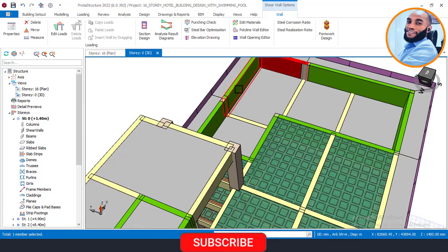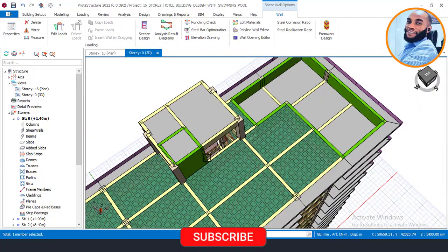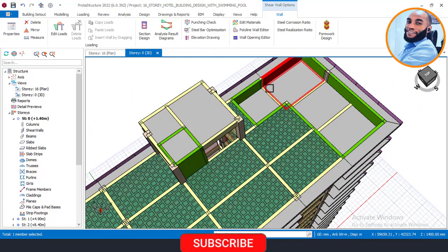Now, this load is only applicable on the retaining wall around the pool. As you can see that we also have a retaining wall for the lift. So don't apply the load on the lift, only apply the load on the wall.